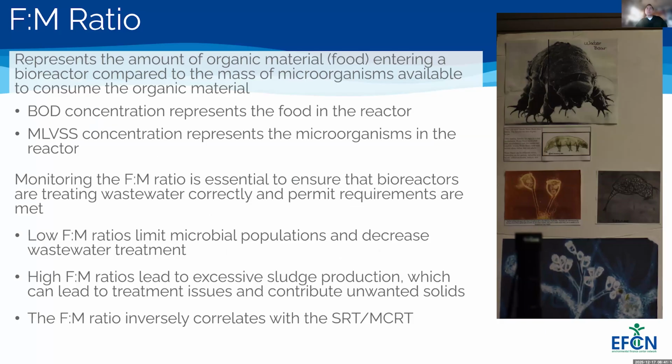So that brings me to the second calculable variable that we're going to talk about, the F to M ratio. This is our food to microbe ratio. It represents the amount of organic material entering a bioreactor compared to the mass of microorganisms available to consume that organic matter.